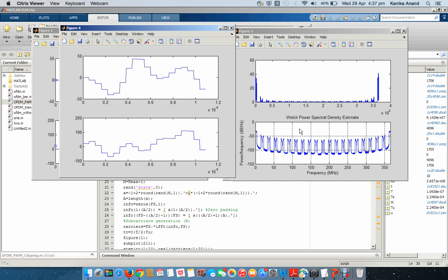Now we can see that the frequency response is periodic, as required of the frequency response of a discrete time system. The first thing to notice here is the delay of approximately 2 into 10 raised to the minus 7 produced by the filtering process. Aside from this delay, the filtering performs as expected since we are left with only the baseband spectrum.